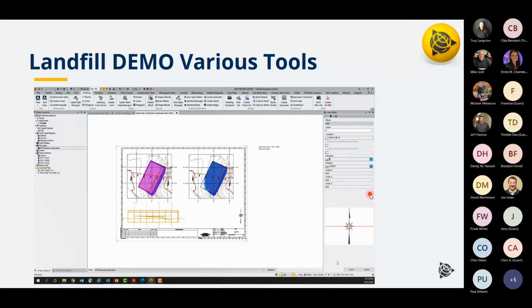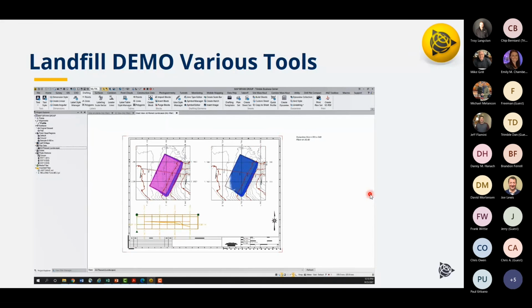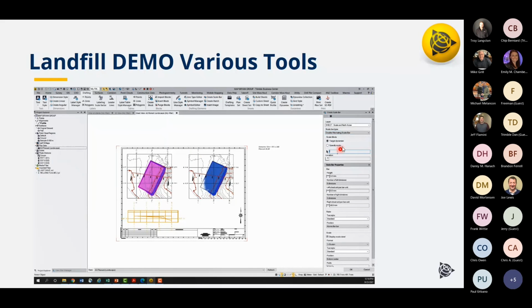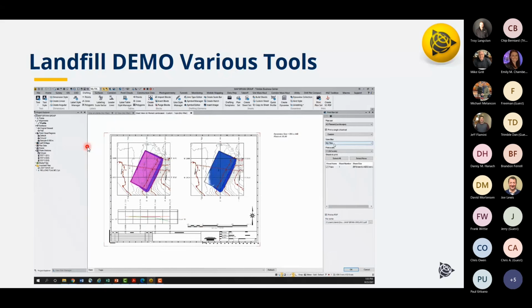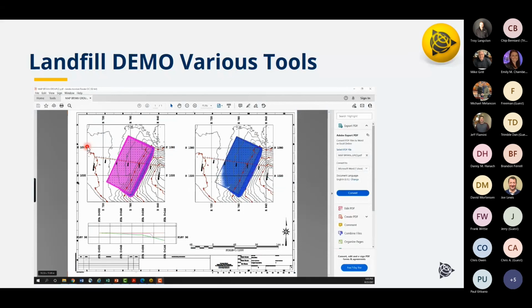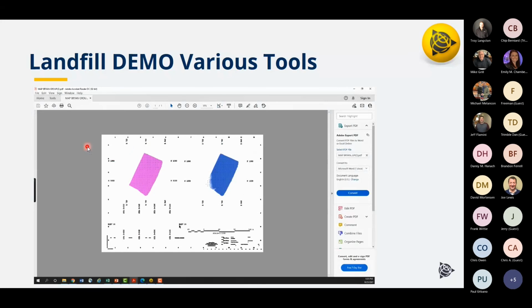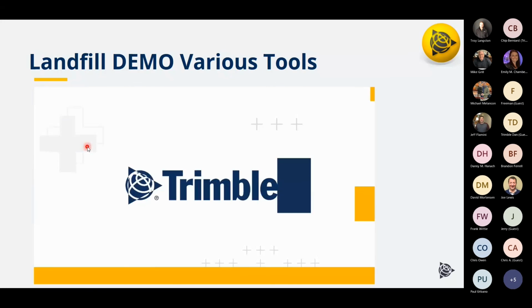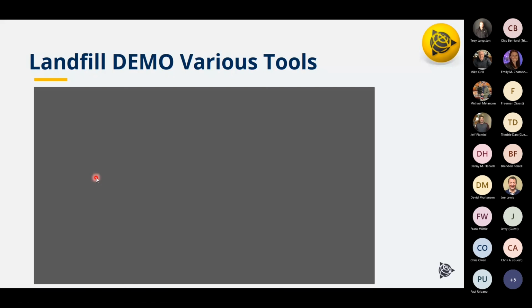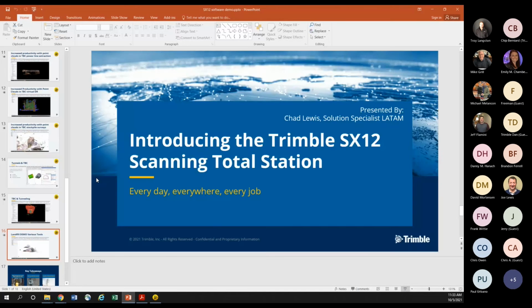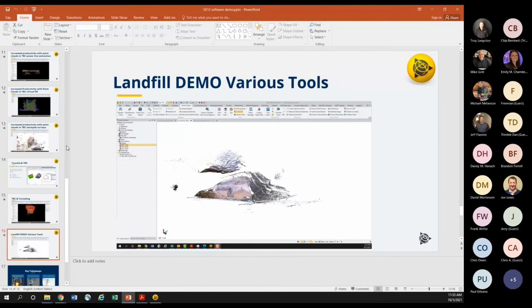And with the scale bar, one of the interesting things is I can just tag the Dynaview here, and that'll set the scale automatically. So we were using 1 to 1200 on this. There's my scale bar. I put that in place. And then the next step is just simply printing that off to a PDF. And there you go. We have a deliverable, in this case, the landfill and whatnot. So just a quick overview of Business Center and some of the deliverables that we can achieve here.